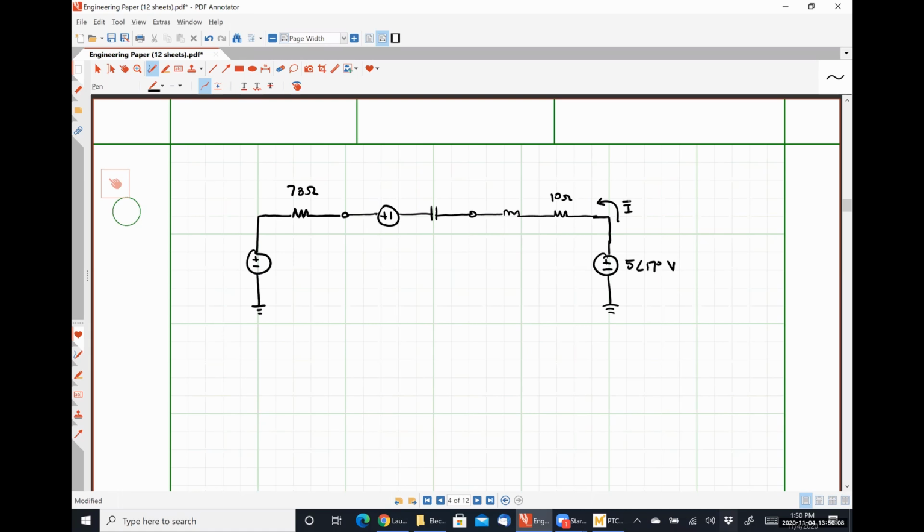All right, so what was the impedance of my capacitor? Because I've forgotten, I'm too lazy to scroll up. I think that was my inductor. Negative J4 there, J13 there. All right, so this guy is going to have a value of 40 angle minus 45 degrees milliamps multiplied by 73 ohms.